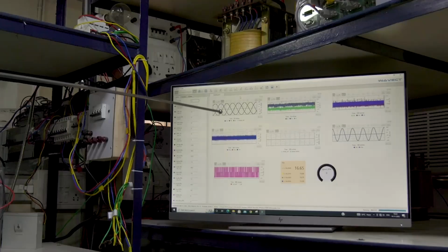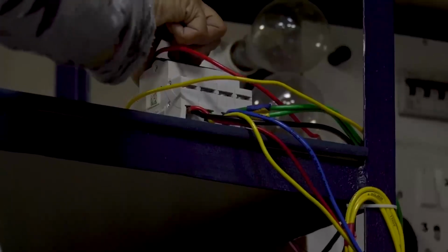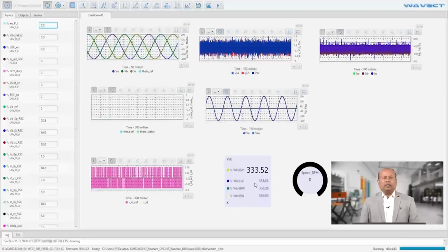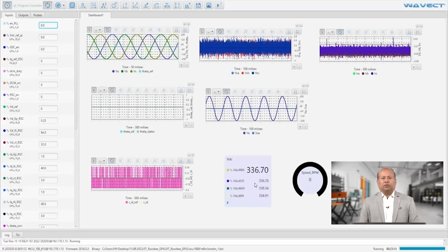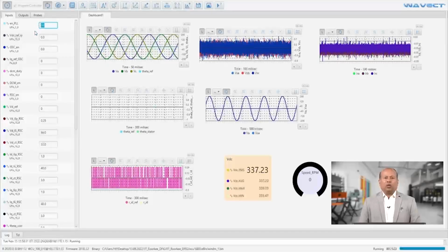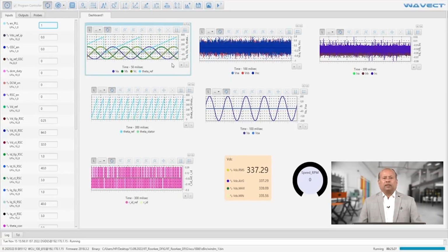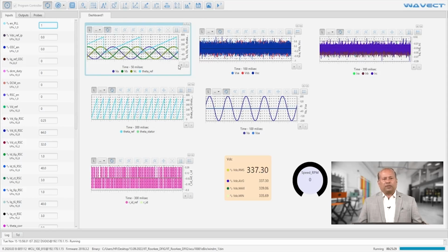The main and the rotor branch circuit breaker is switched on and the DC link is charged initially to 340 volts. Then we enable the phase locked loop and check the reference theta with the phase A voltage.